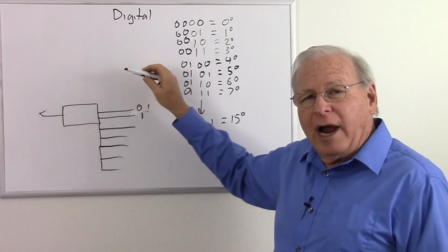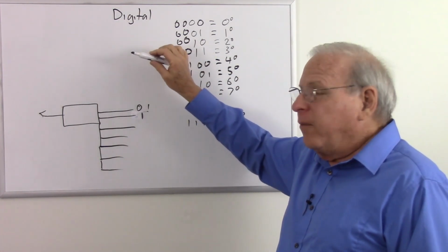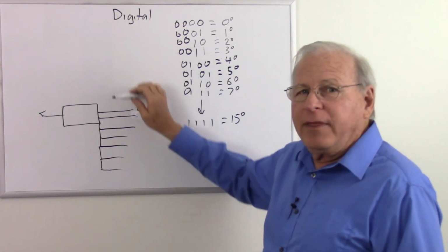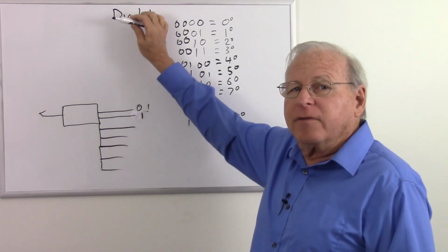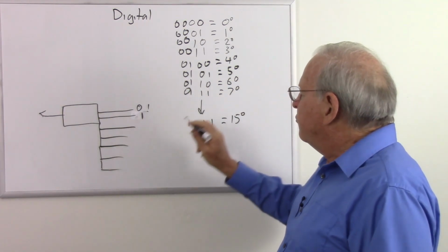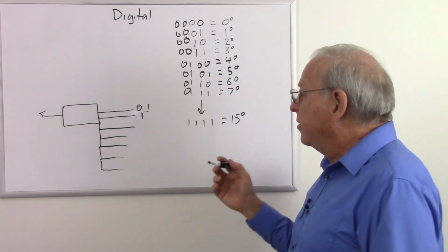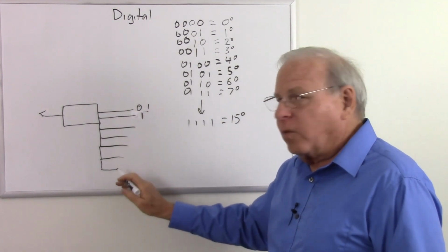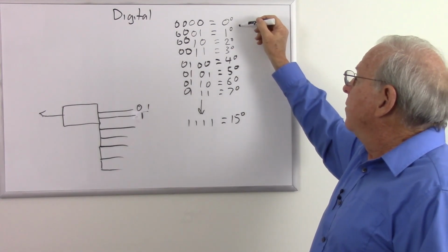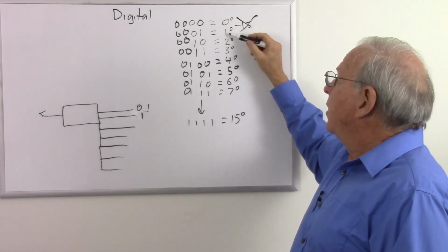So we had that single wire, and we were able to go from 0 degrees to 100 degrees on that one wire, and we could have any fine division we wanted in between there. So we could have an infinite number of steps. Well, here, not only is it taking me 7 wires just to get up to 100, actually to get me to 127 of the 128 steps, but to get to that 100, I need 7 wires. And I don't have any steps in between. I cannot go to 1.5. Not allowed. I can go 0 to 1, 1 to 2.